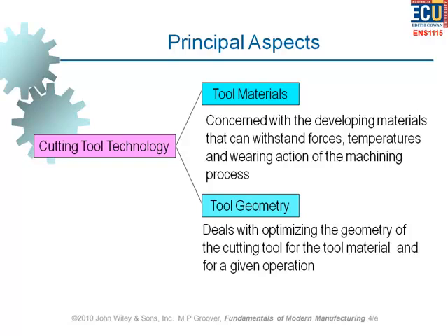Ductility. Ductility, is that what you mean? Sometimes ductility is actually of importance in the selection of the material, but not always. As we know, ductility and hardness are inversely proportional. When we increase hardness, we are sacrificing what? Ductility. If you increase ductility, then you are lowering hardness. And more often, in cutting tools, we are after a high hardness rather than ductility.